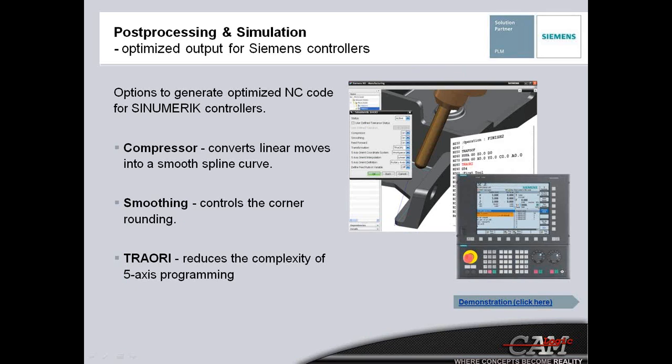For any customers that are using a Siemens Sinumerik controller, NXCAM also provides an optimized Sinumerik post processor that automatically selects key controller settings based on machining operation data. A special menu in NXCAM can enable you to select key functions on the Sinumerik controller. Let's take a quick look at an example of this.